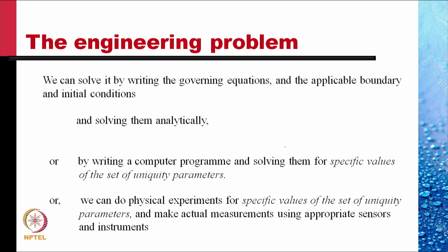Thus, we could make the aircraft wing fly with this airfoil, have ports on the wings, along the chord, along the surface of the wing, connect each of these ports to a pressure measuring instrument and measure the pressure when you fly the aircraft at a given speed, in a given atmosphere, with a given density, with a given viscosity, and so on.